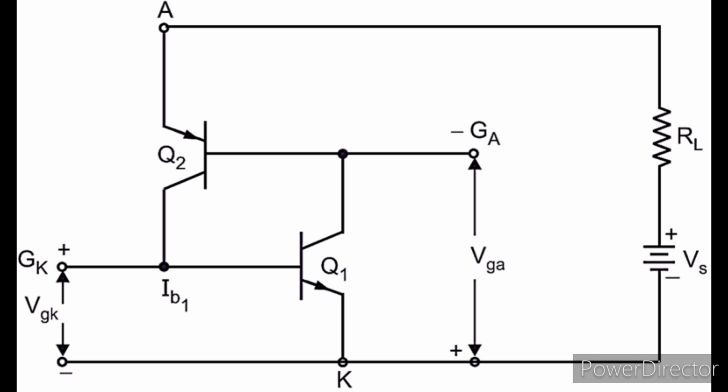Now, when we want to switch off the device, the role of gate terminal G2 comes into the picture. A positive pulse at the gate terminal G2 turns the device off because the gate terminal G2 is connected to the N1 region. This stops the regenerative action that had been established earlier and turns the device off, stopping the flow of holes and thus increasing the reverse bias at the N1P2 junction.